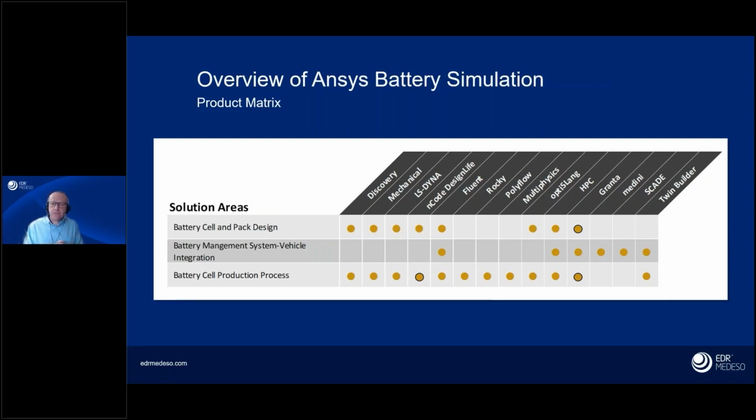If we're looking at durability, well, we can consider nCode DesignLife. That's really good at looking at fatigue and thermal fatigue problems, and it's a very full-featured package for doing that. You can do a certain level of durability within, say, Ansys Mechanical, for example, but if there are some really advanced features, then we can consider nCode.